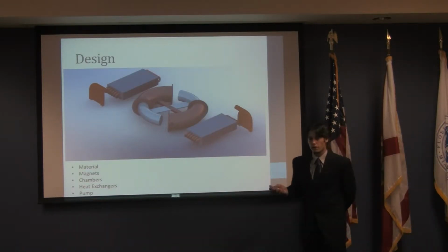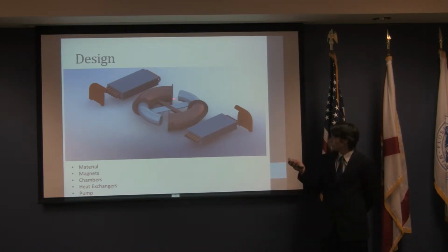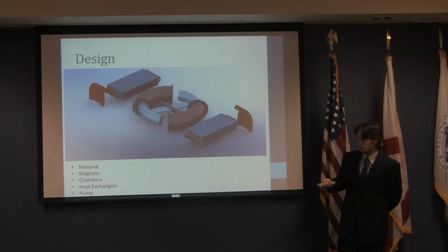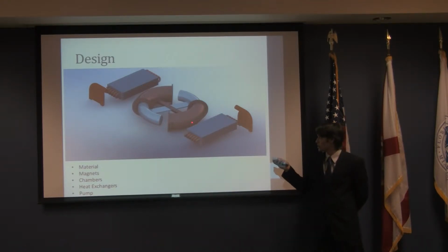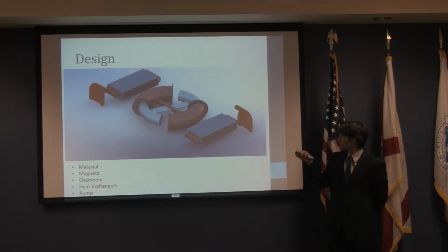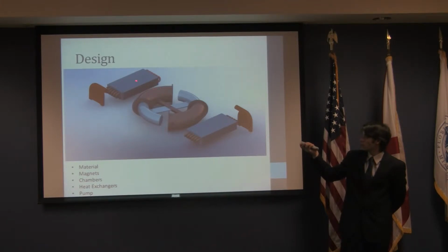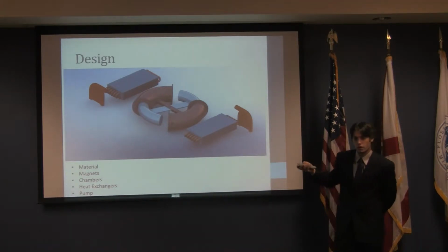As you can see here, we have decided to go with a circular design. The reason we're going with a circular design is because at any given time, the material will be in either of the 2 heat exchangers. This would be the heat rejection heat exchanger. This is the cold side heat exchanger. So pretty much, there's going to be water flowing through here. Inside is a concentric tube heat exchanger on this side and a plate heat exchanger on this side, water to air cooling.